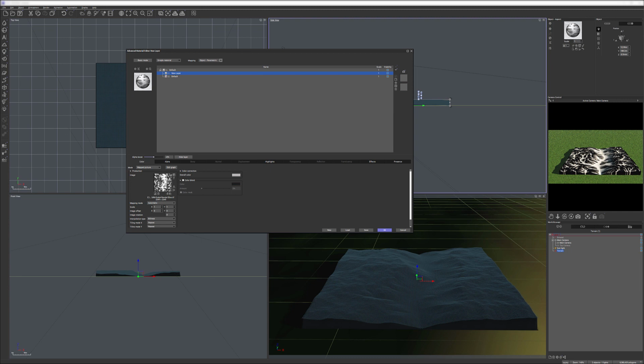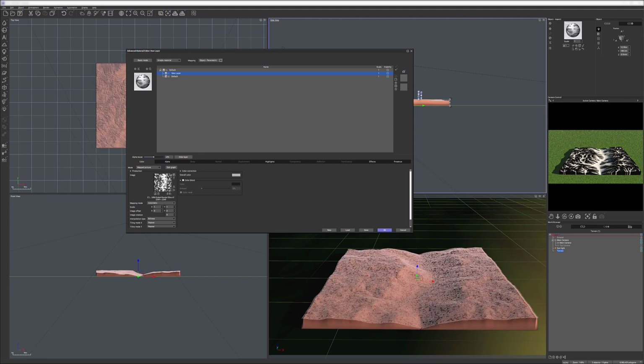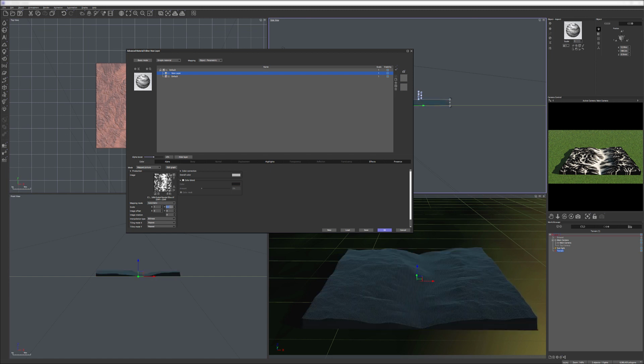Remember I mentioned stretching, which is kind of important, and I found out because when you work with a terrain, it is square. If you saw, the size was 2048 by 2048. So I want to be sure that if I'm applying my image on top, it will match the size of my terrain. If not, the stretching could go very wrong. So for example, if we go right here and change the stretching, you can see how it now starts repeating from the size going right here.